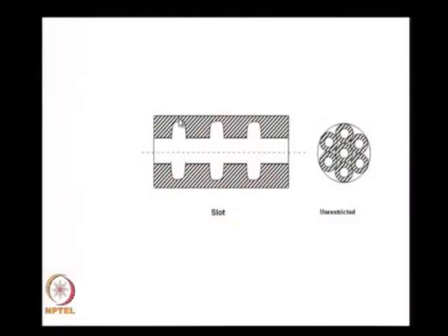And I show a 3-dimensional surface over here which is a slot, and it continues to burn in this direction, in this direction, but the problem is a simple geometric problem. I want to find out how this initial burning surface area, this is the perimeter into the length, how this keeps increasing as the regression of the surface continues. This is a slot.